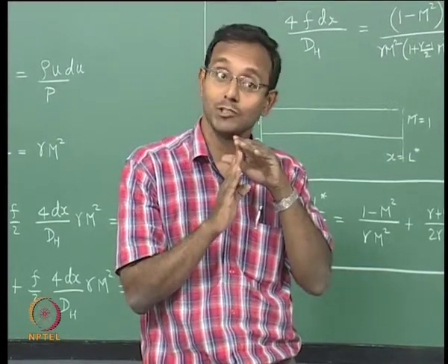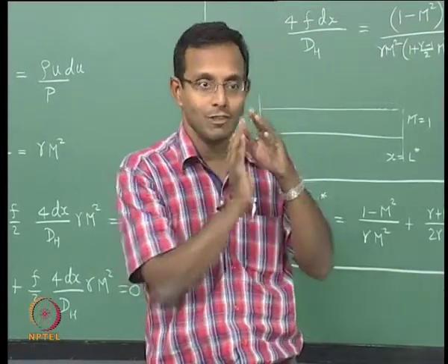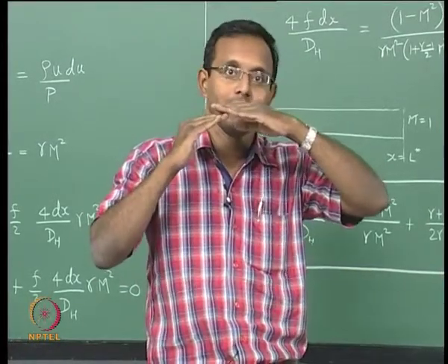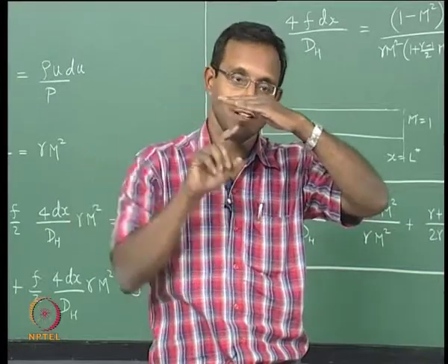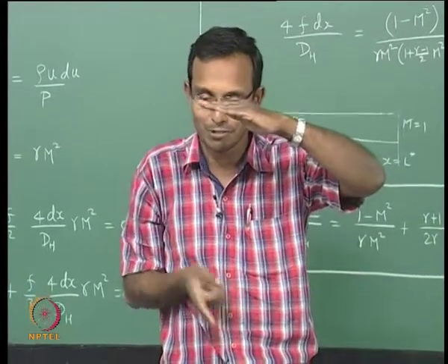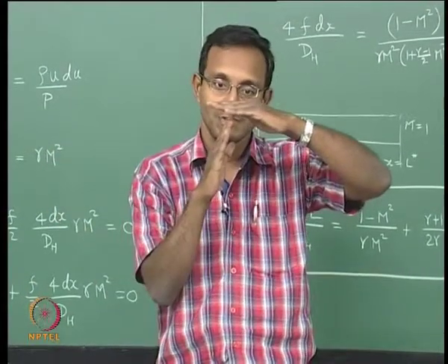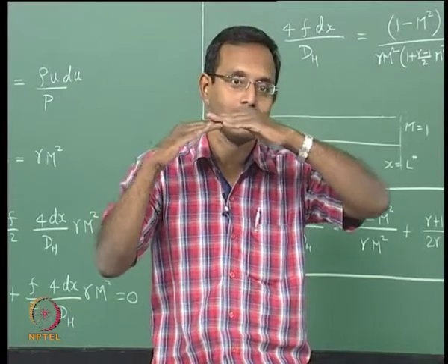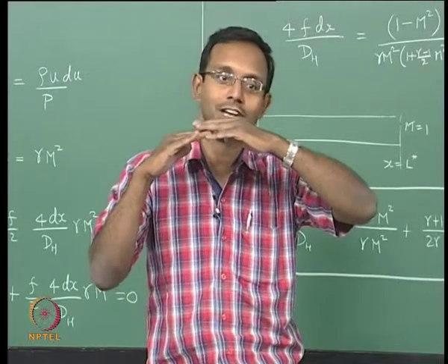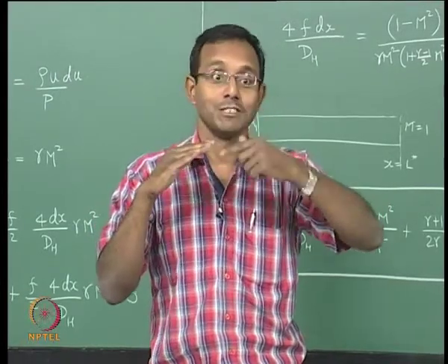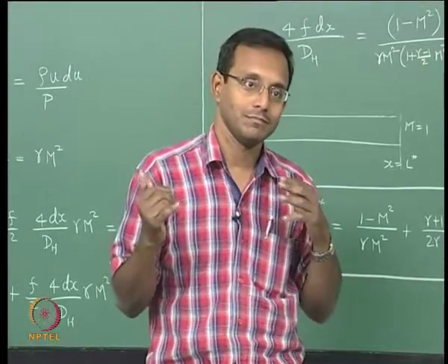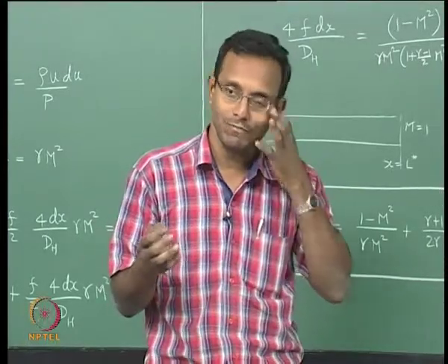But the same thing if it is supersonic flow, then velocities are much higher. That means the velocity gradient will be very, very high. If the velocity gradient is very high, my velocity profile will be more like this suddenly, instead of a subsonic flow velocity profile like this. Velocities are very high, wall velocity gradients will be very high. This is supposed to be from fluid mechanics, I am assuming you know fluid mechanics. So when the wall velocity gradient is very high, friction will be much higher. So friction has a huge effect when the velocity is very high, which is expected, right? It is expected from fluid mechanics anyway.